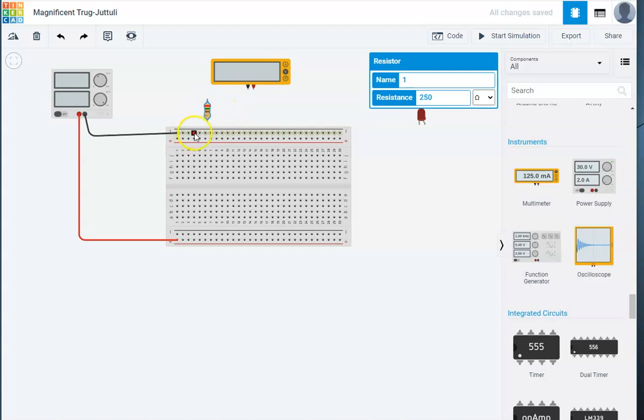So I'm going to use the resistor to jump from this negative row. Okay, in essence, I need to make a connection. I need to connect this wire to the resistor. Let's think of it that way. Okay, so if I'm going to connect this wire to this resistor, I need that point, one of the ends, to be connected to any one of these other little holes, and I've made a connection.